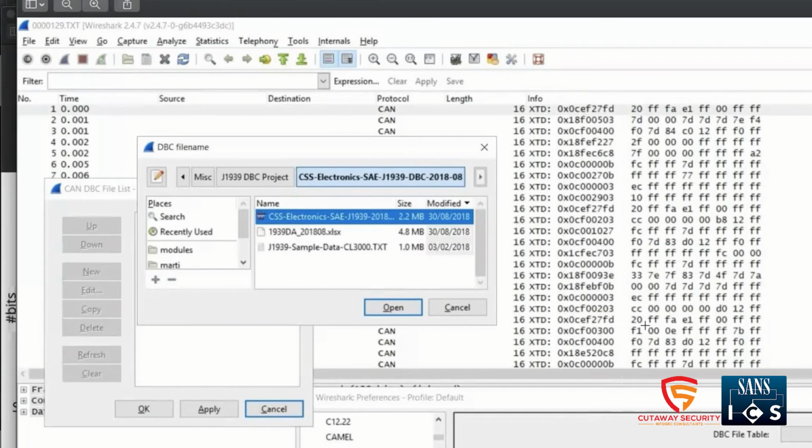You've got 2 ways of figuring it out. You can either get the official DBC files that are going to translate between these numbers and the actual meanings for each of the messages, or you can reverse engineer it yourself, which is going to take quite a bit longer. But it might be your only option because some companies aren't really open about this stuff. So the CANbus standard is more of a way of passing information. The format of the data is specific to vendors, possibly following some formatting standards, but really whatever their engineers designed it for. Is that kind of the breakdown?